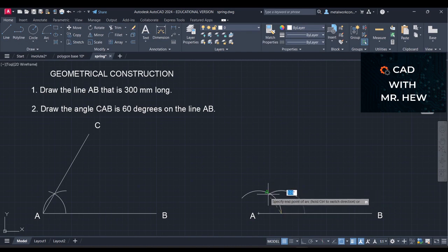Here. See that? So the line drawn from A going through the intersection of these two arcs, that is where the 60-degree would be. That's a common geometrical construction in math, technical drawing, or engineering graphics. All right. So we're going to go line. So the compass must be at the same radius. Okay. Enter. All right. Here I've labeled the angle C.